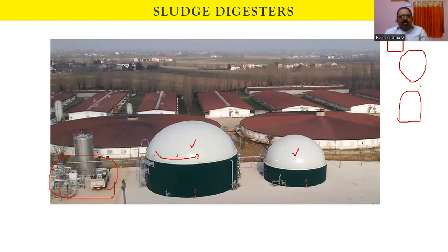But ultimately, whatever design they take, the net operation is sludge digestion, where the sludge is separated into digested sludge, active sludge, liquid, scum layer, and then gas. Gas will be there at the top. It is collected in the dome, which can be a floating dome or a fixed dome, and the digesters operate depending on that. These digesters can be used for different types of wastewater sludges, maybe agricultural waste, and food waste. A number of options are possible. So this is all about different types of digesters as well as the design parameters of digesters. Thank you.